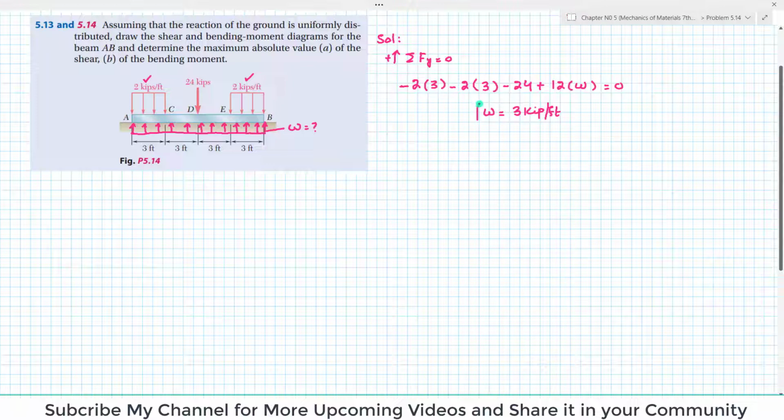So this is the value of the uniformly distributed load that the ground exerts on this beam. Now for finding the shear force and bending moment at each section, we will section the beam at various locations. First we will section the beam at this point. This section is 1, from A to C, which means x is greater than or equal to 0 and less than or equal to 3 feet.